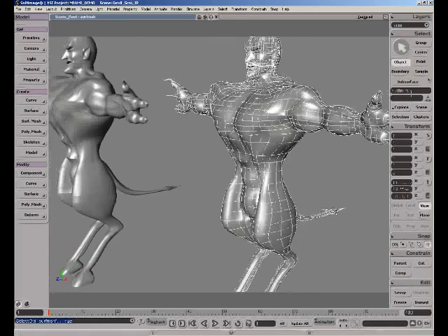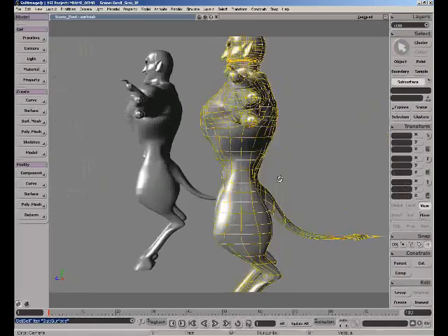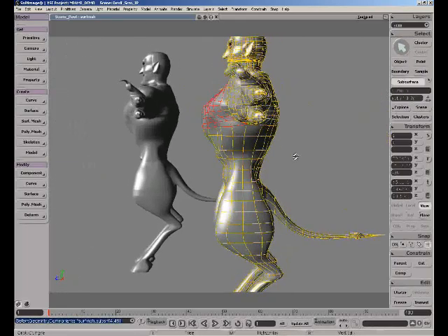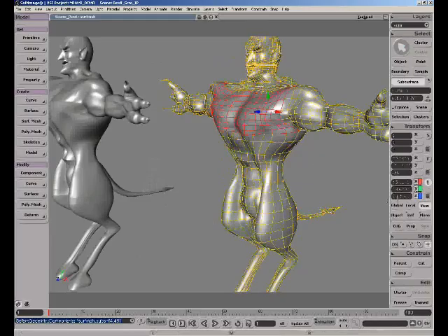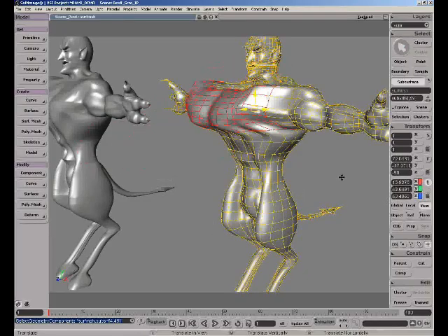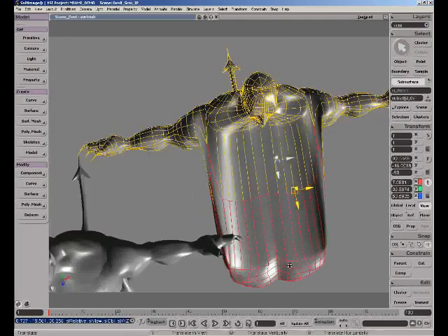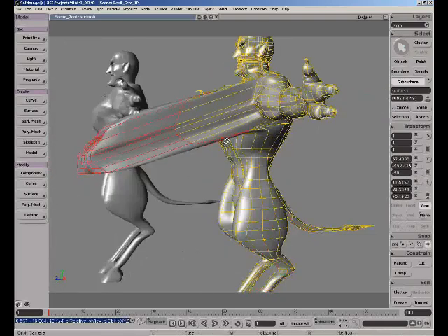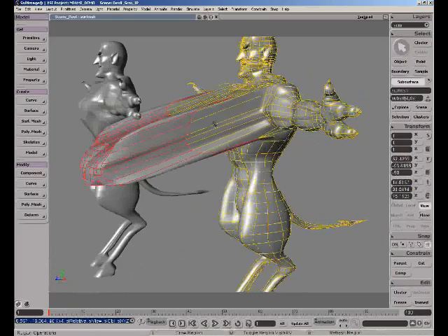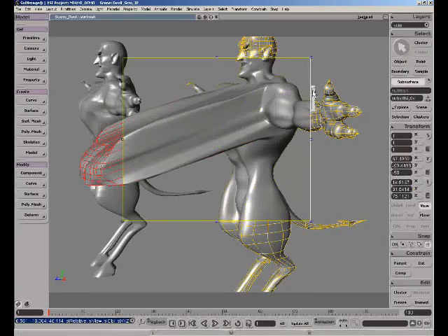Well, what's cool here, though, is you can still select individual subsurfaces. So, for instance, if I go ahead and grab these two here, I can pull these out. Look how fast it is. It's not slow at all. You can still modify those existing pieces of geometry and just go ahead and pull that way out like this. Let me just show you that we don't get any tearing. We'll go ahead and draw a render region. It's a beautiful, seamless piece of geometry. You can throw texture maps on this as a single piece of geometry. You can put inverse kinematics chains in here, bones, whatever. An incredibly powerful tool for making a seamless character out of NURBS objects.